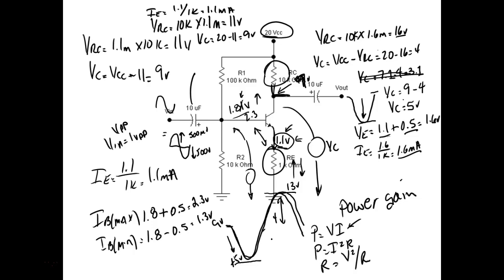And this is where you need to know what gain you expect. We need to know what gain we expect before we actually calculate the gain. So I'm expecting a gain of 10 out of this amplifier. But according to our calculations, I'm getting 8 volts peak to peak out, 4 up and 4 down.